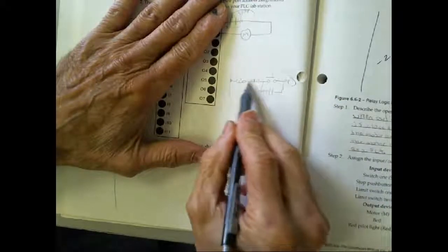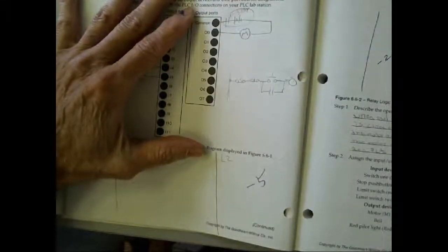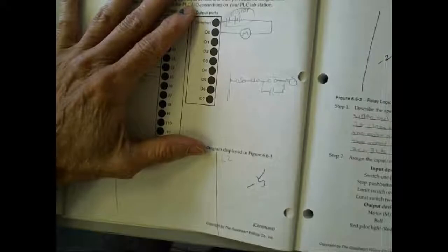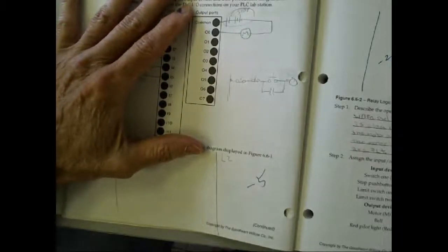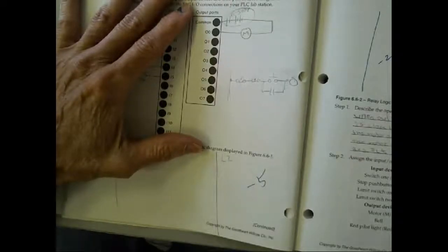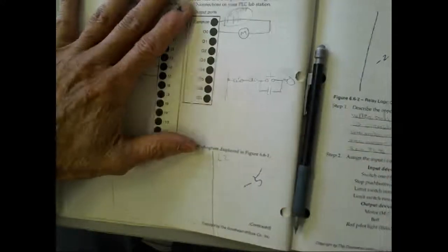And then here, you might have a series of strings. On number 4 galvanized line, we had, good gracious, like 30 E-stop buttons hooked in series. If anybody came up and hit one of them, it would stop and drop the line. What was happening is they would hit an E-stop button if they wanted to take a break, and we had to go over this line, three stories high, up and down trying to find which E-stop button. So we put in a panel. They bought some E-stop buttons that had lights on them, and we had an E-stop light panel, so if somebody hit it, you could see exactly which one. A lot of E-stops have a light circuit on them.